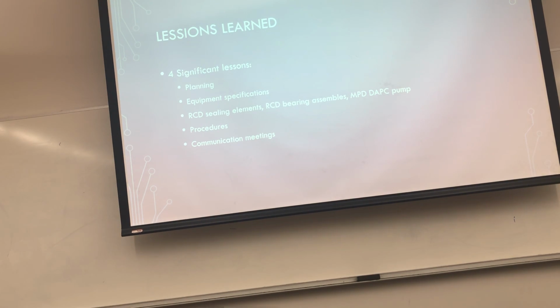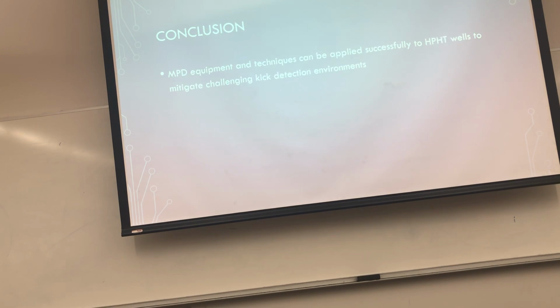And the four lessons that were learned when reading everything were planning, equipment specifications, procedures, communication meetings, RCD sealing elements, bearing assemblies, and the DAPC pumps. Those are all the most important things that need to be planned and basically talked about before even drilling to have a successful operation. And in conclusion, basically, MPD equipment and techniques can be applied successfully to high pressure, high temperature wells to mitigate challenging kick detection.